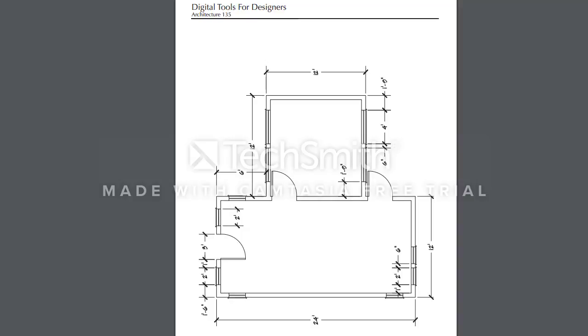Okay. I see a hand raised? Yeah, go ahead. I noticed some of the dimensions on the windows are missing. Yeah, we don't give you every single dimension. Actually, all of these windows are exactly the same. So notice that this one is called out as 2 feet. All of these windows are actually 2 feet. This one is called out as 4 feet. I think actually everything is dimensioned at least one time. That's kind of a standard architectural practice in a drawing.